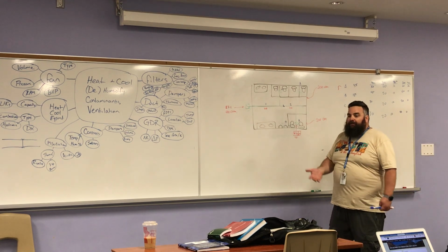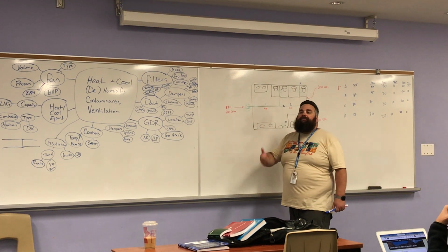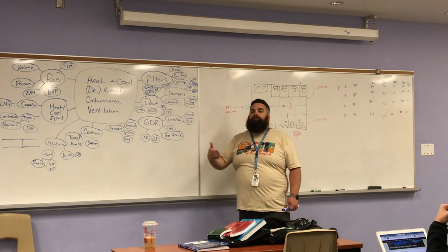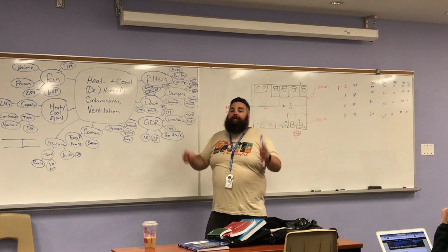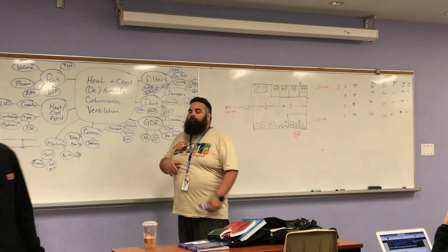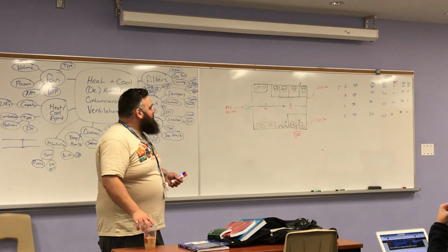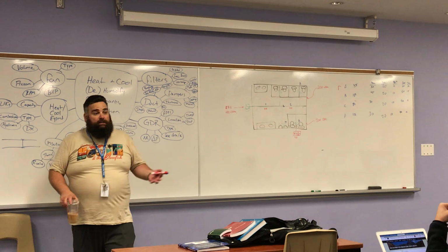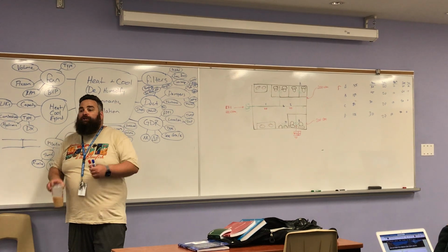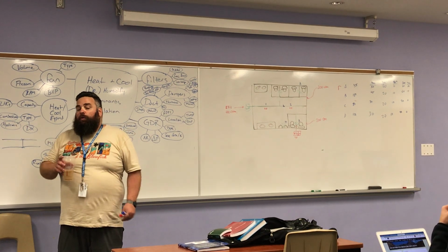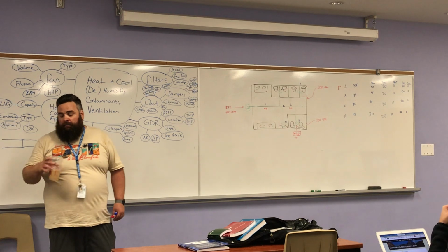That's what we mean by equal friction method. Regardless of the length of the duct, we want them to have the same frictional loss or the same pressure drop. That way it will be self-balancing. We still need balancing dampers, because nothing's perfect, but that's the intent. That's what we're going to do in this class. We're going to do this in much greater detail, okay?